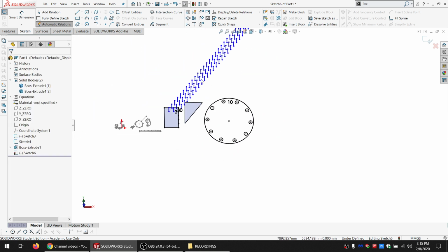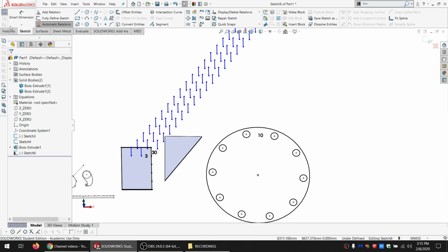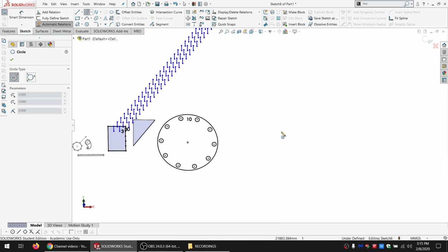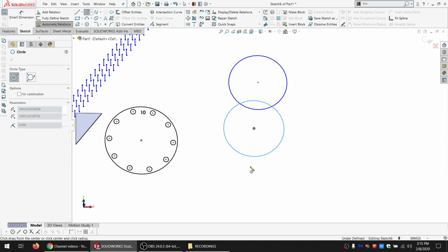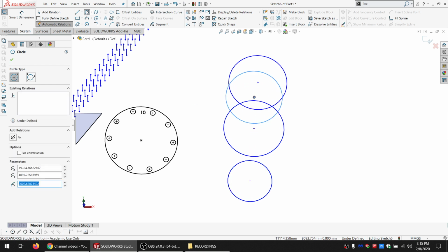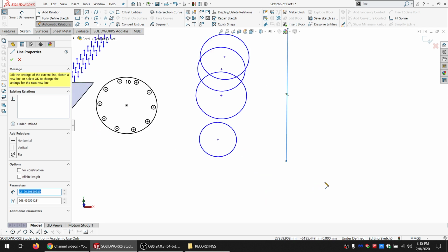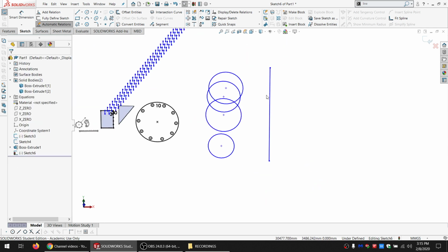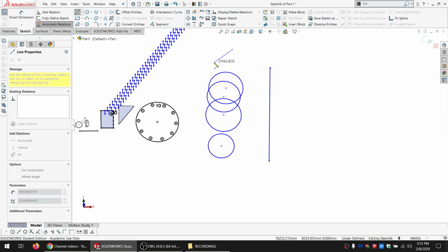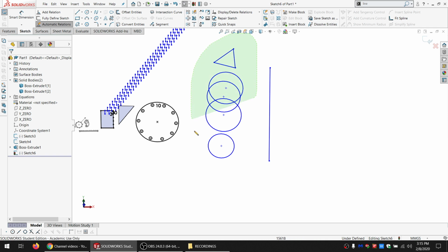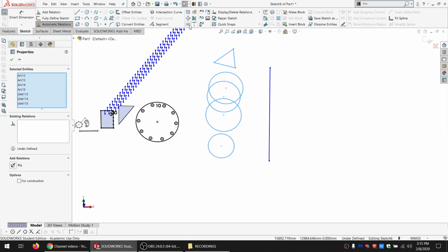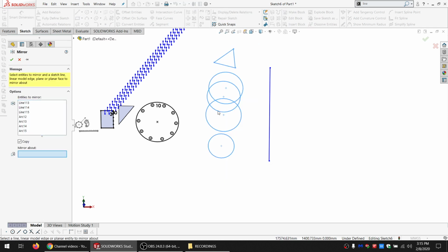down. So next one is mirror. So let's say I've got this, and this, and I've got a line, and I want it to be an exact copy but backwards. So just to make it a little more obvious, I'll draw that in as well. So I'm just going to select all these. I'm going to say mirror, and then I'm going to click here.